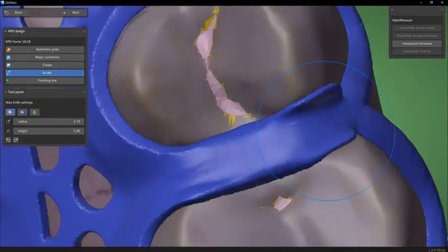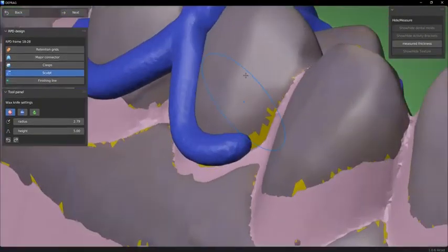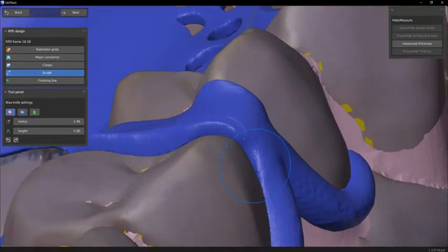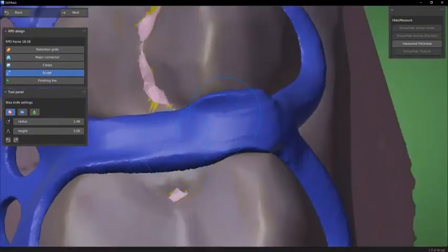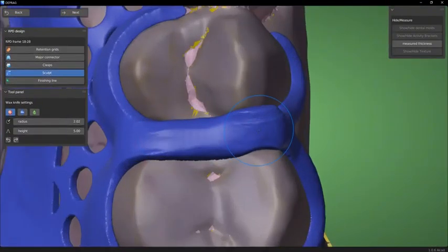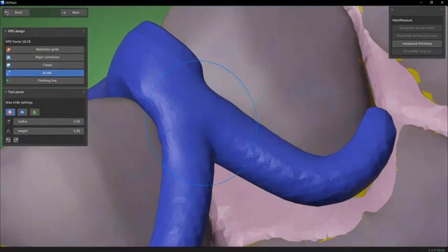To measure the thickness in the engraving interface, you need to right-click the mouse on the surface of the bracket to complete the thickness measurement at this point. But except for this page, you need to left-click the mouse to complete the thickness measurement. It's different.